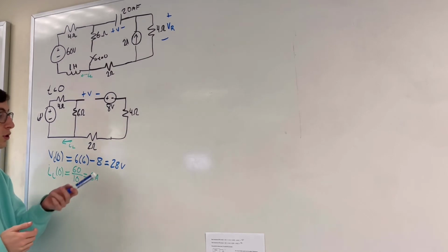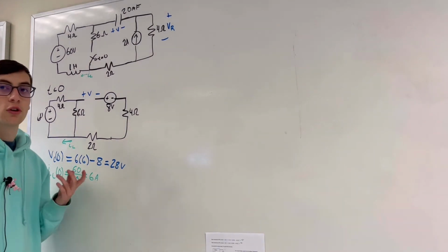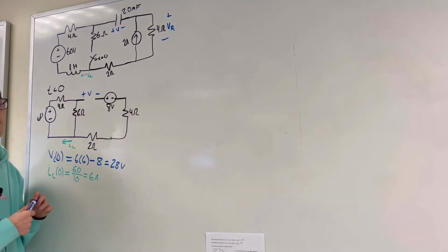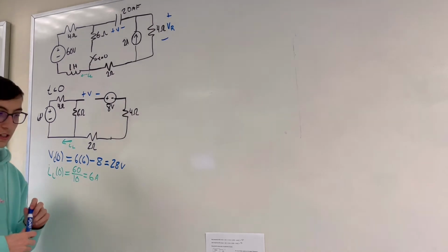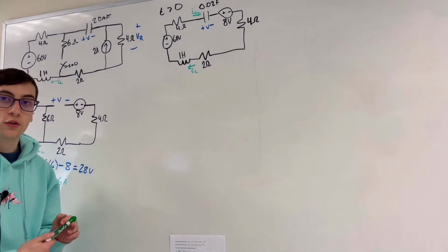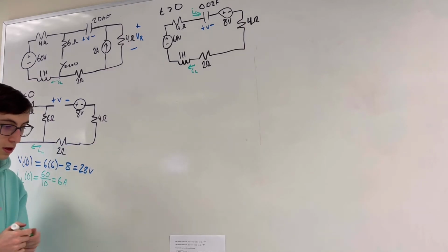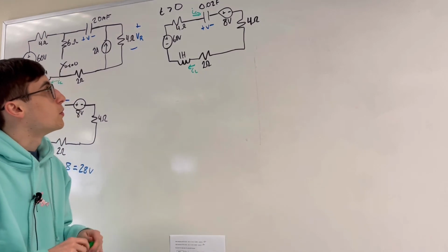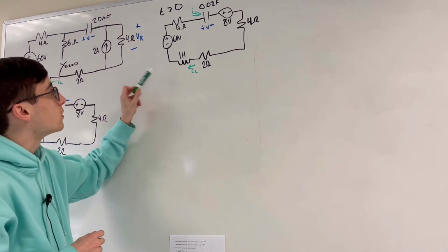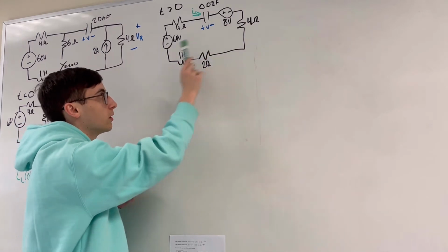Now that we have these two initial conditions, we're going to find our circuit when time is greater than 0, and we'll find our final initial condition of dV of 0 over dt. To do that, we first need to find IC. But we know that IC is just equal to IL because in this circuit, they're both pointing the same way, going around this way.